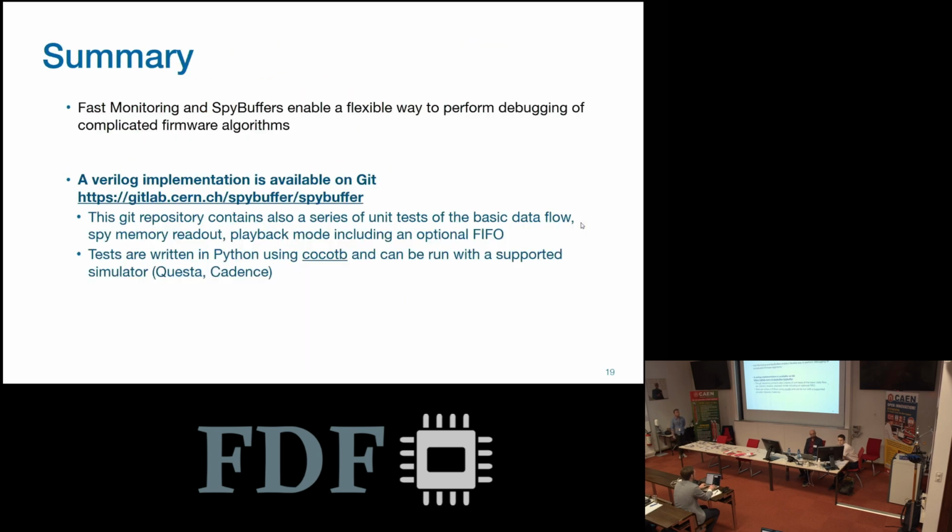And just to wrap up, the fast monitoring and SpyBuffer are a relatively simple way to perform debugging of complicated firmware logic, and if you need an implementation, it is available on this Git repository. This Git repo also contains the unit tests that are written in Python, and they use CocoTB, and they can also be used to regenerate the waveforms that are shown at the beginning. And that was it from my side.